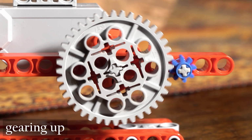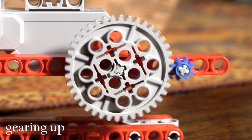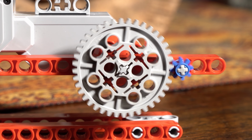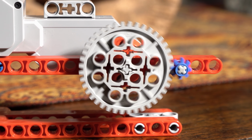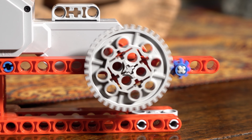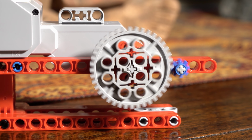Anytime a larger gear powers a smaller gear, the gear ratio will be less than 1, which represents gearing up, in which the speed of the driven gear is faster than the speed of the driver gear. As this speed increases, the available torque inversely decreases. If a simple gear train cannot produce the required speed, a compound gear train can be utilized.